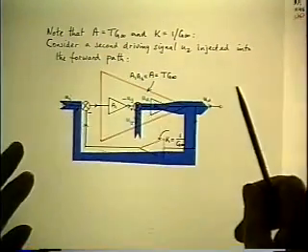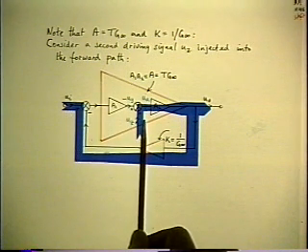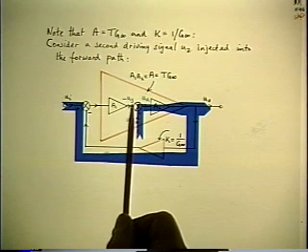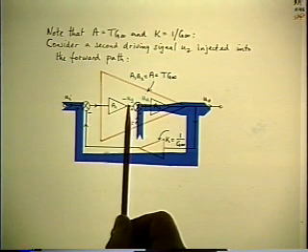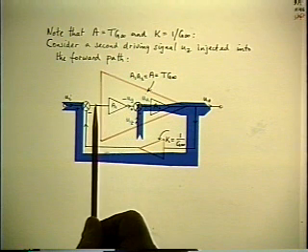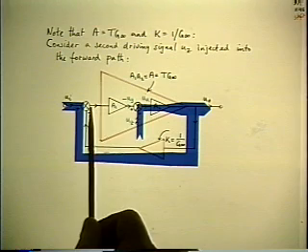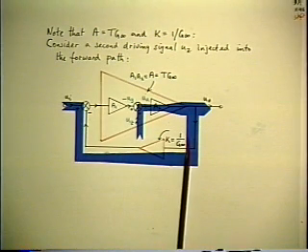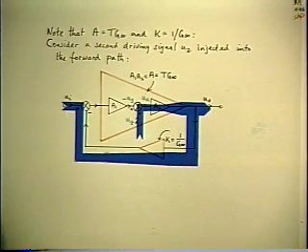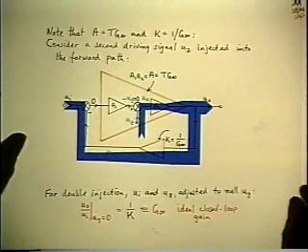So this is the signal distribution that you set up. Two sources, and you adjust them to null the UY, because if you null UY, it propagates back to null the error signal as well. Under that condition, you then calculate UO over UI, and here are the quantities that go with it.